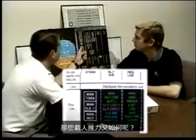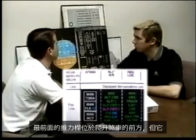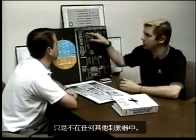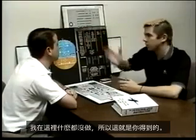What about MAN THRUST? MAN THRUST is, the auto thrust is armed. The most forward thrust lever is forward of the climb detent, but it's just not in any of the other detents. It's basically a default for, hey, I'm not in anything up here, so this is what you get.